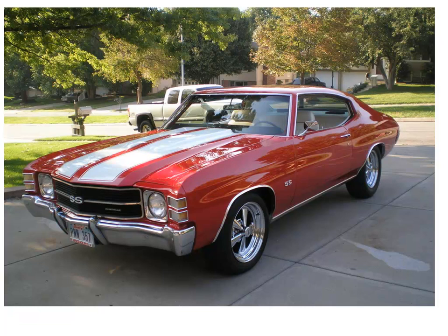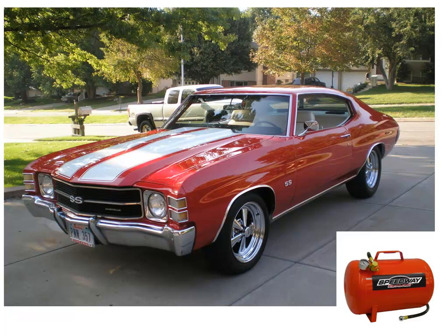All right. When you say that the pressure in the tire is 32 psi, without even saying it necessarily, you're already saying that that's relative to atmospheric pressure. You're implying that that's relative to atmospheric pressure. That's not the absolute pressure of air in the tire, but that's how much additional pressure is in the tire compared to our Earth's atmosphere. And so one important thing that we have to differentiate between is gauge pressure and absolute pressure.